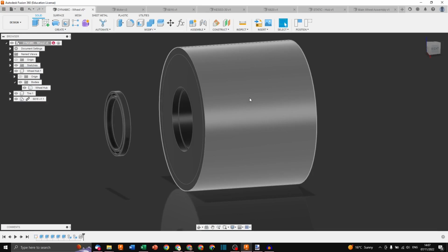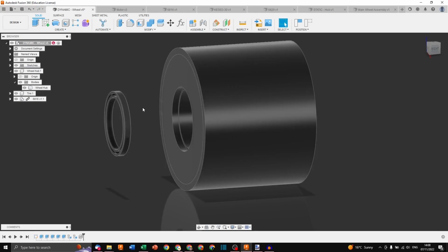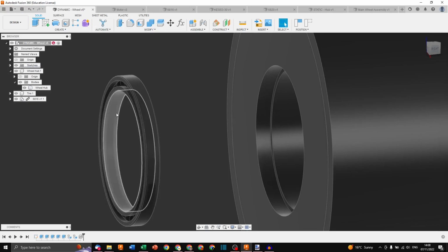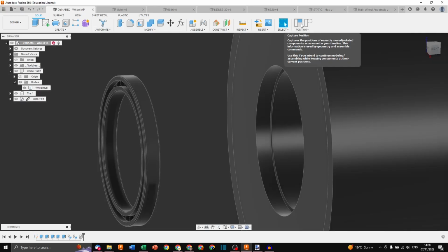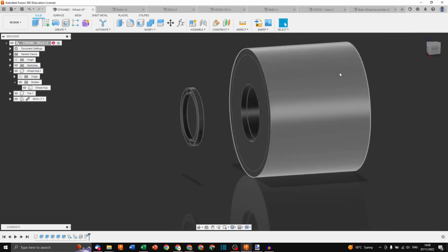When you have moving components in your design, your base position will change because you'll, for example, have a bearing that spins, and now this race will be spun compared to this race. So this tab will pop up, showing you that you've moved your design. When you press this button, it's going to capture the current position and set it as the normal position for your design. So if I capture now, basically, that's how my design will always be.